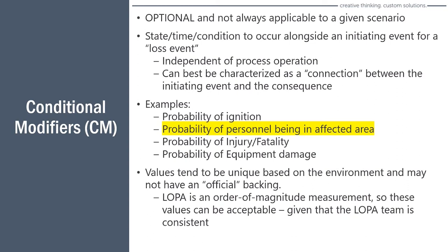It's that kind of thing. And so you do get some credit for that. You get credit for a conditional modifier where you've designed your process such that it's remote, or there's no interaction, or you have done other things that make it more inherently risk averse than if you were just running it as a normal process. And so sometimes you do have these conditional modifiers that some people would call controls or safeguards, and they could be. But again, either way, you want to take credit for that because that is something that has reduced your risk.